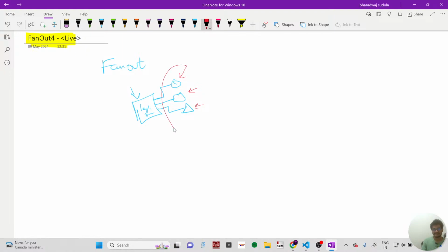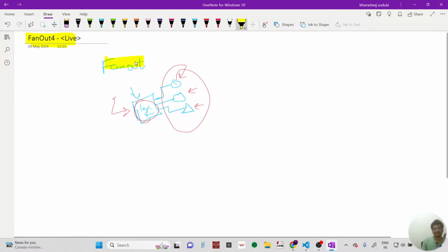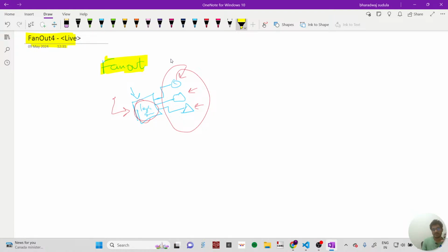It has to charge these gate capacitances. For that, we need some driving strength for this logic gate. So fan-out is a term that describes how many gates, or how much load, it can bear in such a way that it can properly charge these load capacitances.